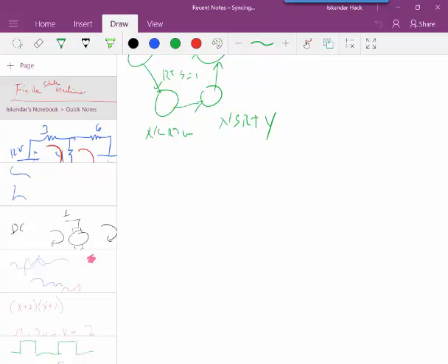The reason is VHDL allows parallel processes. And this is a side note: VHDL or Verilog is a way of designing field programmable gate arrays or customized ICs. And when you design a customized IC, you're allowed to set up parallel processes. When we write in C, it does this line, then this line, then this line. That's called a sequential process. It goes through and does everything one line at a time.